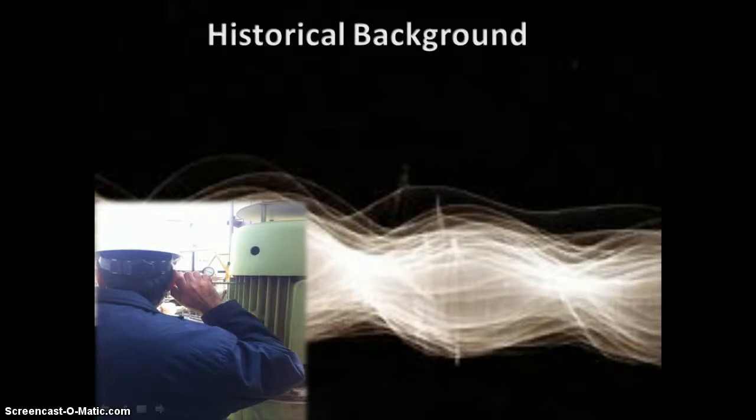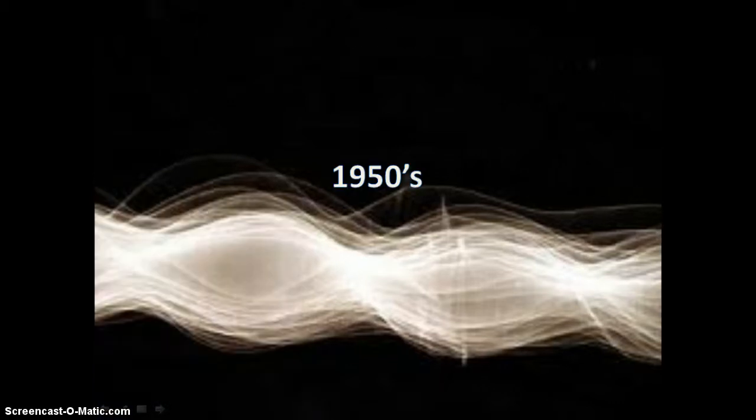The first vibration analyzer was the human brain coupled with the sense of touch and hearing, using a screwdriver on the nearest part to the bearing. The first vibration meters were introduced during the 1950s and measured the overall or broadband vibration reading. These first vibration meters were analog meters. A little later, tunable analog filters were added to the meters in order to make it possible to discriminate between frequency components, giving breadth to the vibration spectrum.